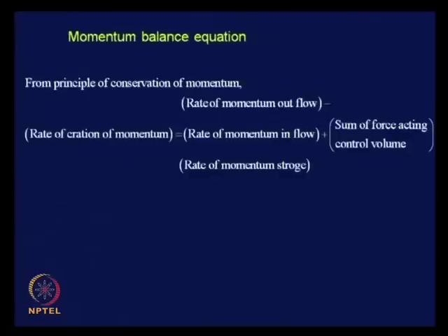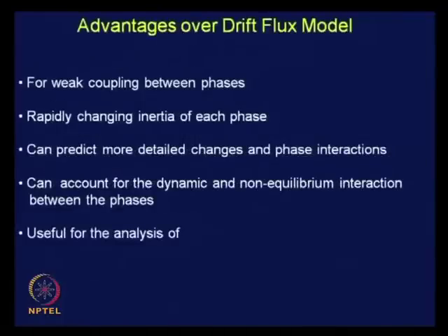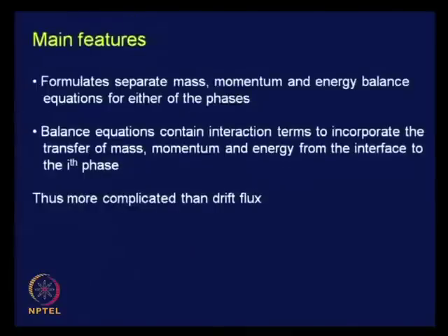Well, so we will be continuing our discussions regarding the separated flow model. This was one extreme of the situation, the homogeneous flow model being the other, where we considered that both the phases are intimately mixed with one another, whereas here they are totally separated from one another. As I had already discussed in the last class, the best thing is that we consider the two phases separately, and we formulate separate mass, momentum and energy balance equations.